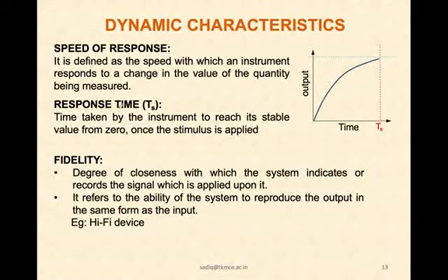Again, another term is response time. That means it is the time taken by the instrument to reach its stable value from 0 once the stimulus is applied. In this diagram, we can see that this is the output shown and this is the output that we expect, a stable value. So the time taken by the instrument, once the input is given, to reach the stable value is called the response time.